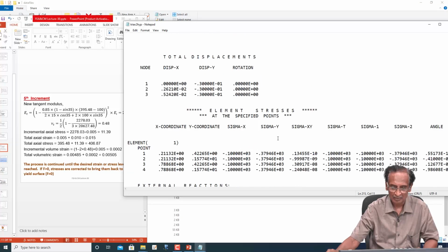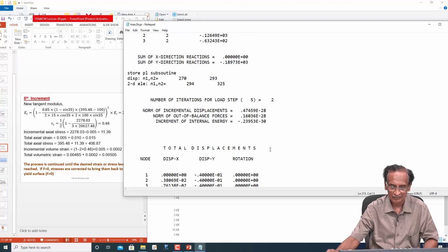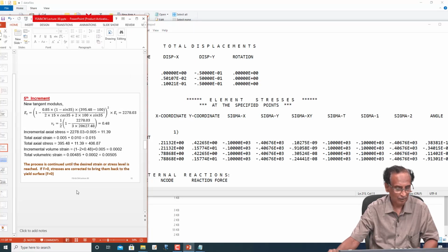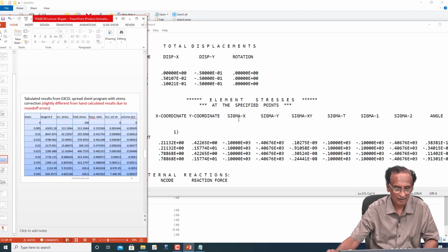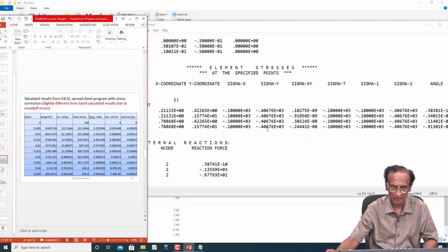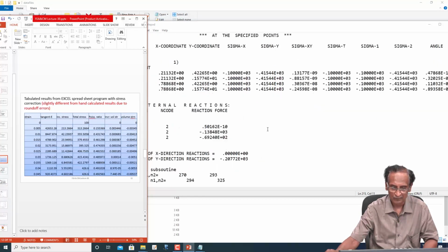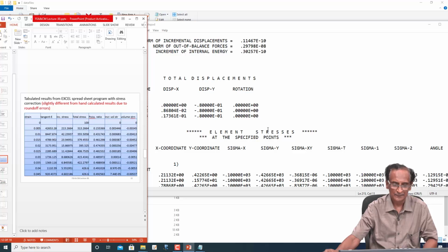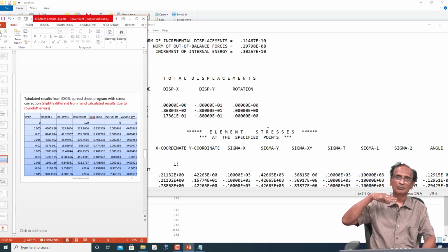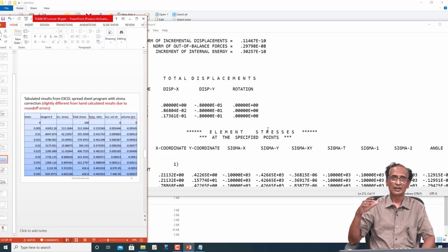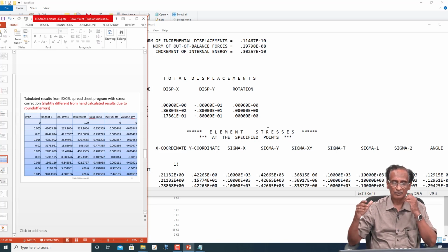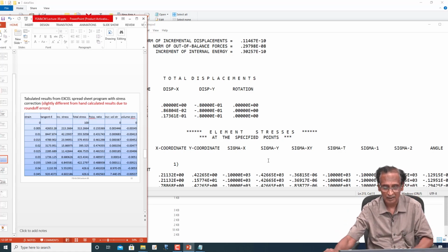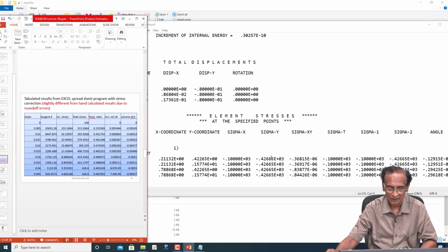And then the stress is increased to 379, and then 395, 406. That is exactly the same as how it is increased by hand calculations. And then 415, 422, and then at this stage the stress has reached the limit state. That F value is almost 0 or slightly increased beyond 0, and then the stress state is corrected back, and now our sigma y is 426.65.